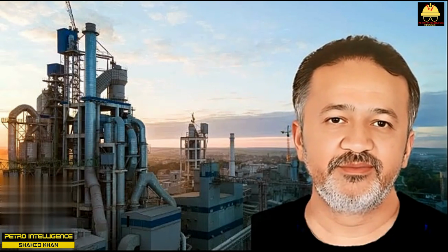So, there is often a practical upper limit on higher velocities. But, putting aside such hydraulic limitations, there is also a practical limit regarding maximum velocities as limited by tube side erosion. When I worked for an oil refinery, our limit for liquids was 10 feet per second. Recently, working with a very experienced process design contractor, their limit was 14 feet per second. My own design criterion has always been 12 feet per second.